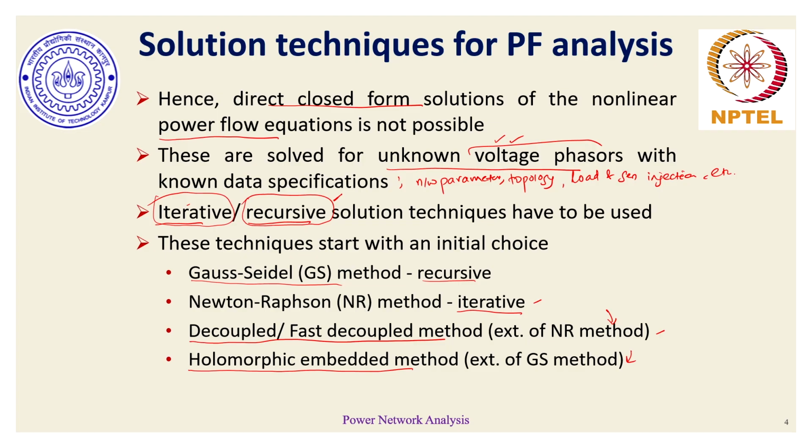So from the discussion perspective, we would discuss the first three topics at length, because these are well-known techniques available in different textbooks, references, and literature papers. The holomorphic embedded method is more of a research technique which still needs some maturity for its actual application. And as I mentioned, most of our industry-grade solvers are based on the fast decoupled method, which we will discuss probably in the next week's discussion as the time comes.